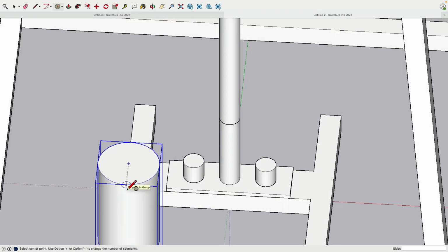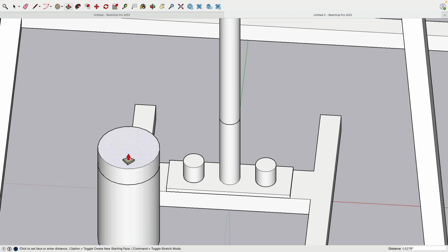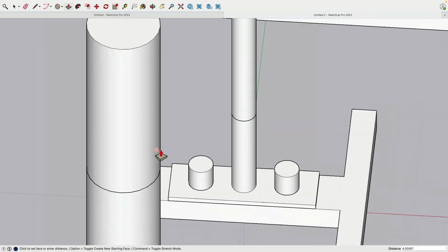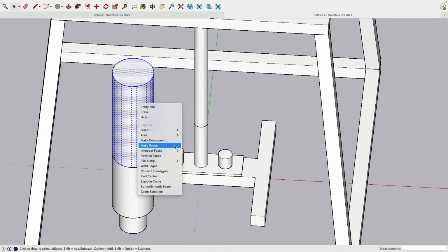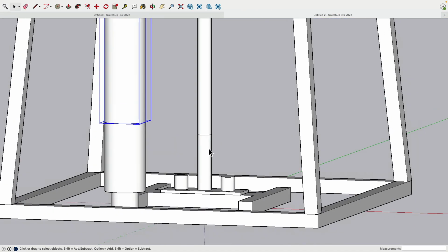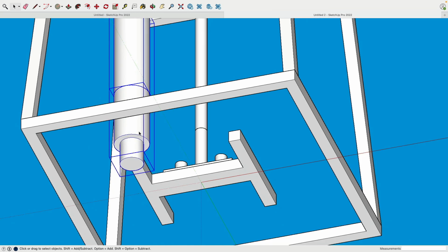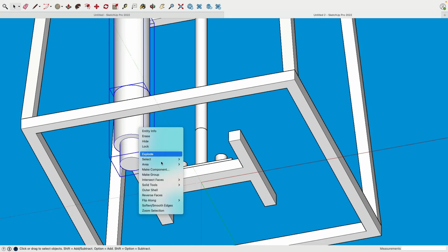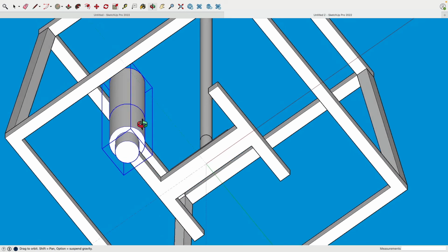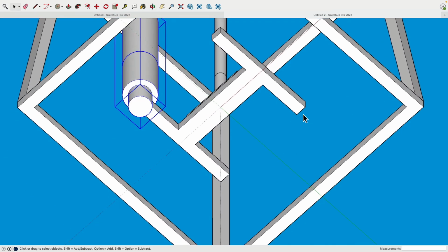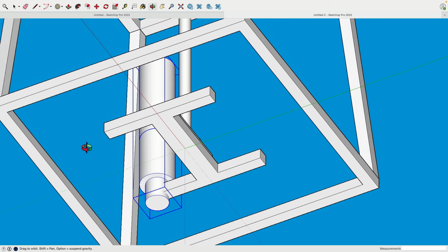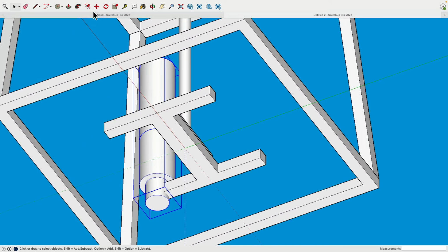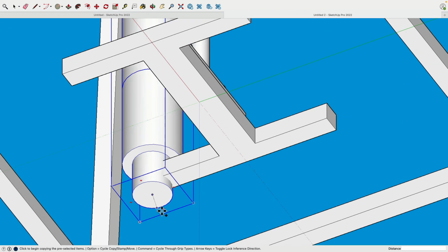One more cylinder. There's the center along the x-axis. And this extrusion is 4 inches. And let's make a group there. Very good. I will select both groups, make a group. You will see why. So how do we position this now onto the other corners? This is not on a circular path. In a very easy way. Well, because of the way we constructed it, what we can do is,